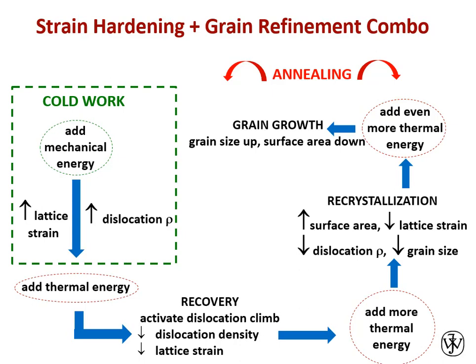We've talked a lot about strain energy and strain in terms of our mechanical properties and being the area under the curve, the energy per unit volume in a material. And in terms of the concept of resilience, the volumetric elastic strain energy in a material. We have strain energy around the ends of dislocations and around solutes.